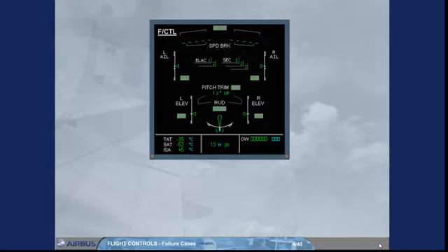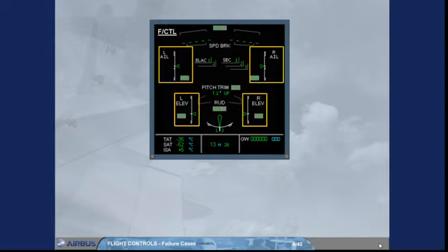Each flight control surface is supplied with different hydraulic sources, 2 for ailerons, elevators and THS, 3 for the rudder and spoilers. Note: each spoiler is supplied by only one of the 3 hydraulic sources. Each hydraulic source operates independently the related flight control surface by means of an actuator.